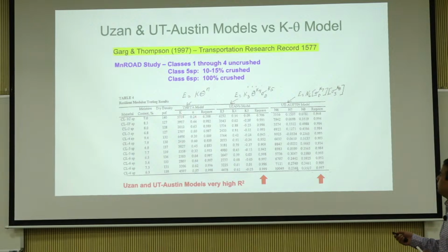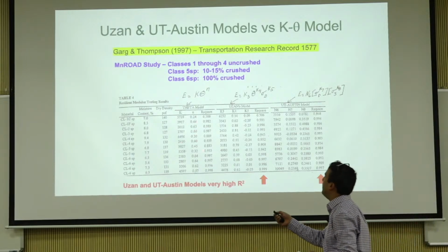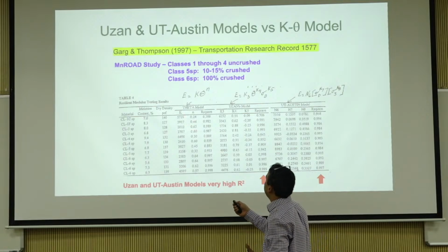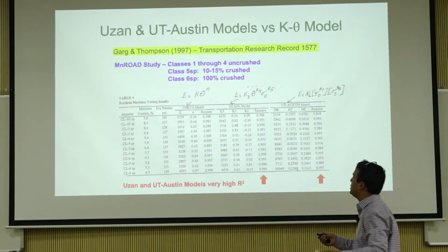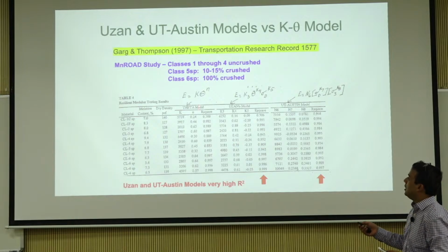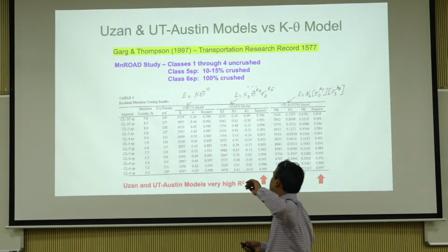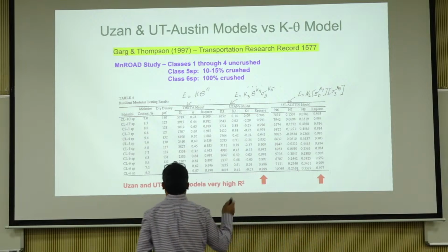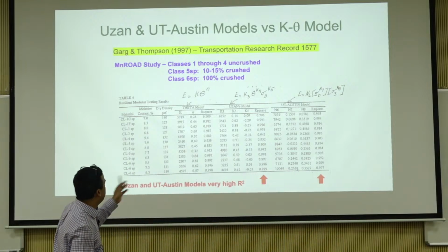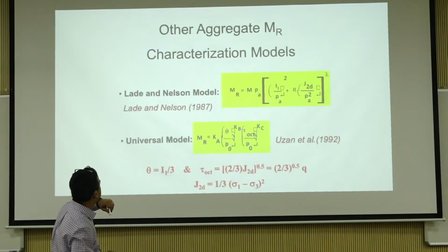This is what I will show you. I'll show you a MATLAB code that I had developed when I was doing my PhD. For all my test results, I used to model everything. I used to fit the k theta model, Uzan model, MEPDG model, which we'll get into, and we used to do some relationships in there.